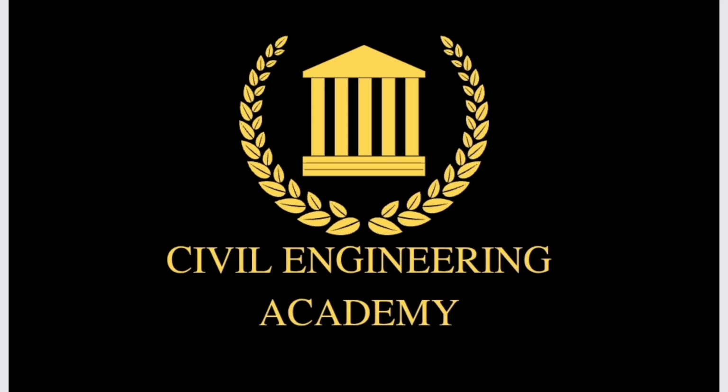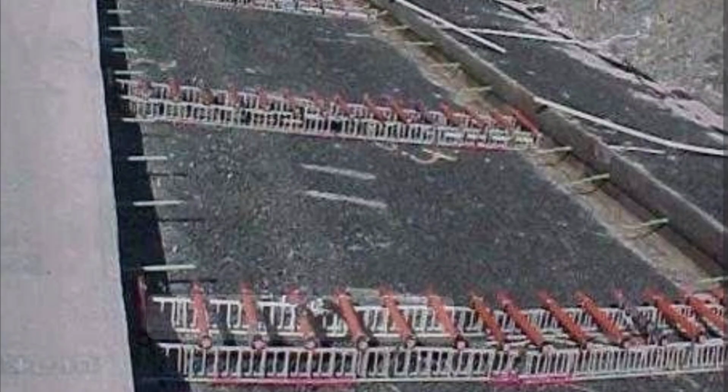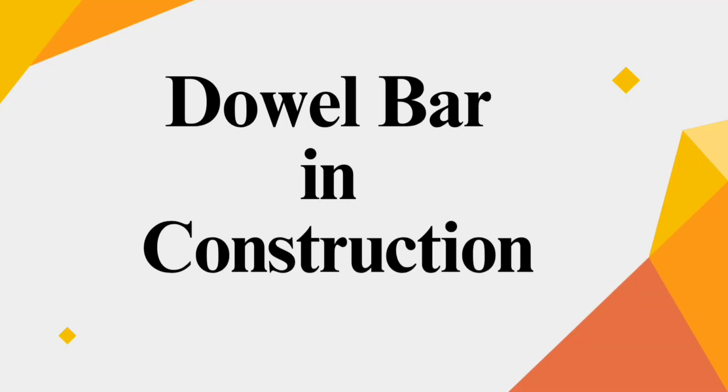Today we are going to talk about a small but very important component used in rigid pavements, that is called a dowel bar. You might have seen steel bars placed at the joints of concrete roads. Those are the dowel bars. But their role is not just reinforcement, they help in load transfer, maintain alignment between the slabs, and prevent cracks at the joints.